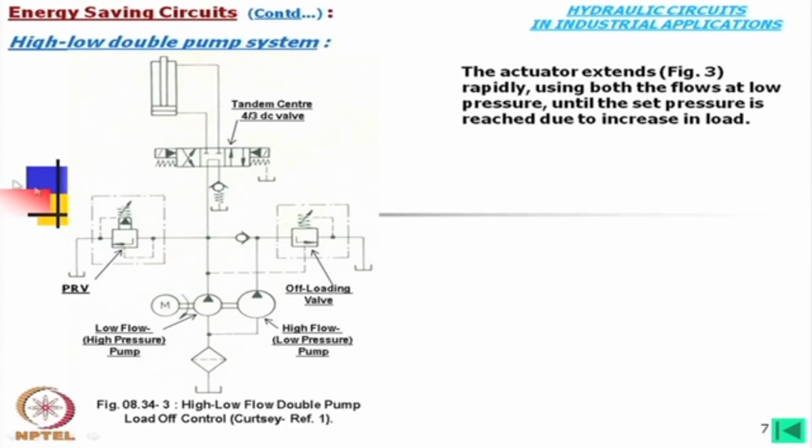Whenever the impeller or piston is moving, the flow is there, and at low pressure there will be less leakage. So, flow is full. With high pressure there will be leakage, but usually the volumetric efficiency of such a pump, in this common case, may be 90%. So, 90% of the flow will always be there, and pressure is always experienced by the load.